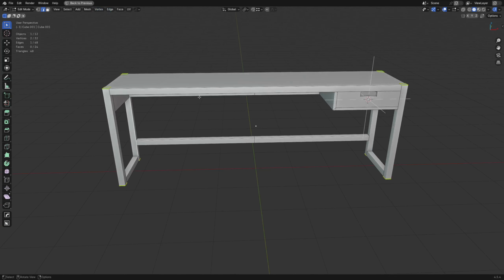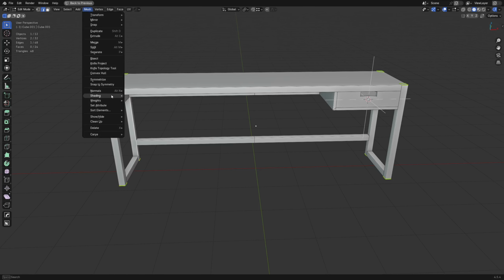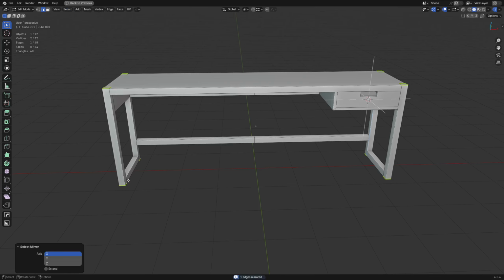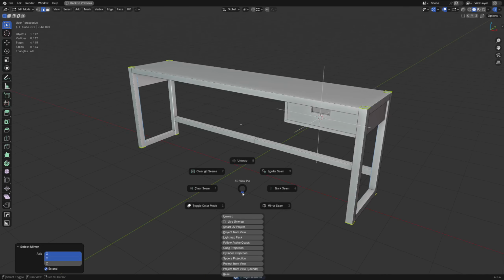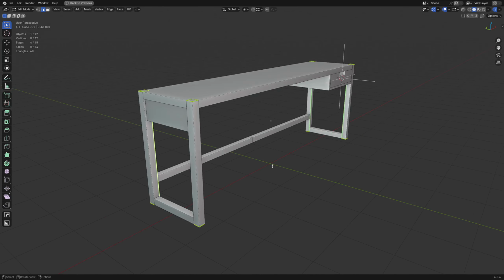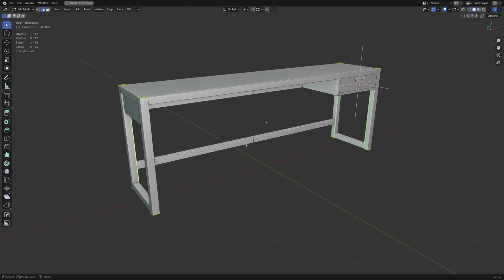So basically what we're going to do is I want to do a selection again. We're going to do a select mirror. All right. And by default, it'll kind of do nothing for the most part, except switch the edge. Just click extend. All right. And then you can hold shift and you can select, in this case, Y. And we can get all of those. And then we can just tag it as a seam, right? We don't have to go manually do all that necessarily. Could be useful to you maybe at some point.